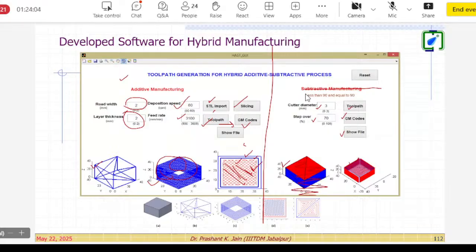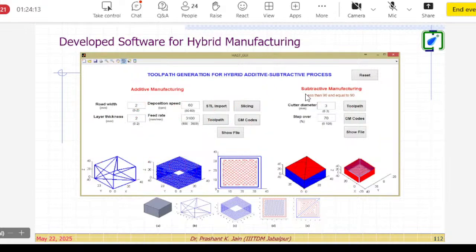Here, this process is done from bottom to top. Here, this process is done top to bottom. And in the bottom, you can see again the geometric model, STL file, contour generation, and toolpath generation, and you see on the top surface there are two triangles. Because I am using the STL file to generate the toolpath, that's why it is working in a triangle fashion. So this is one triangle, second triangle like this, and that is the reason on the top surface, while showing you the machining video, you found there was a triangle like this.